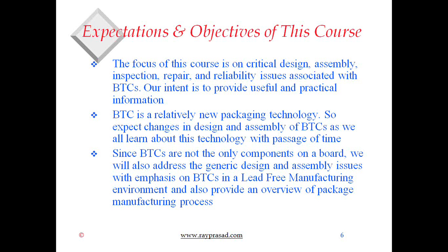The bottom line is that you're not going to have a board that just has a BTC and nothing else, and that complicates the problem. So you have to find a balance so that everybody's happy, because if there's an open or solder joint defect in any component, it doesn't matter what the cause is, this component or that component, we still have a problem.